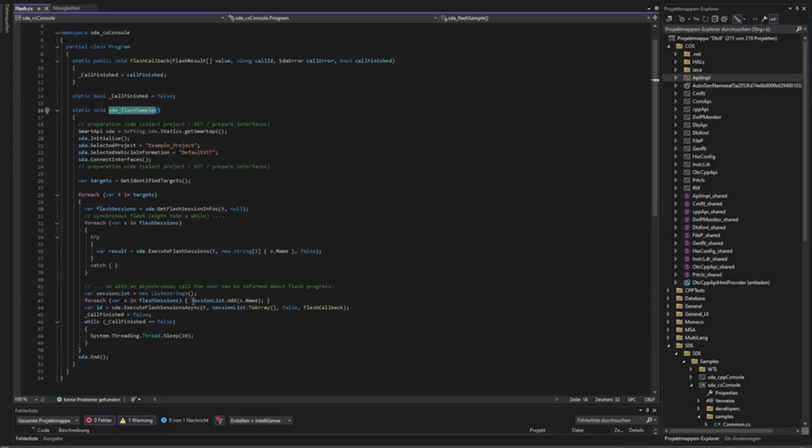If you want to do it asynchronously, it's not much longer. Here, we make it a little bit different. We make a list of all the sessions that we want for the entire vehicle, and we execute this flash session list. We send it down, and here in this while loop, we just wait until it's done. We can do other things here, show progress reports, or do whatever we want while it completes. Again, as I said, if we send this execute flash and we get a connection loss because the vehicle lost its Wi-Fi connection, no issues, it will just continue. Okay, let's go back.